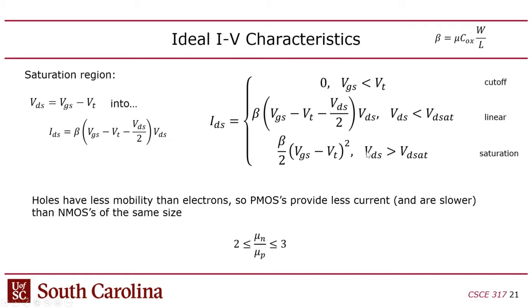I'm not going to get into that, but the important thing to understand here is two things. One is that the length of the channel makes a big difference in terms of the switching time and the amount of current, and also this beta term, the beta is the value that you can manipulate when you design your chip by making wider transistors if you want to.